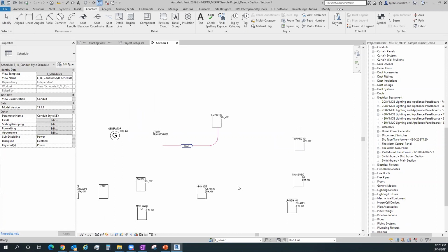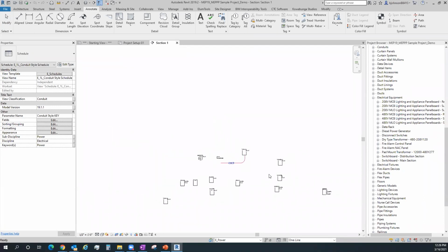Like I say, if we start changing things out, maybe this panel is 150 amps instead of 125. If it swaps, all this data is going to change immediately in the OneLine because it's coming from the real parameters in the real objects. So that would be some of the power that's behind this. They were actually working with real things in Revit. And if we add things, all we have to do is tag more.